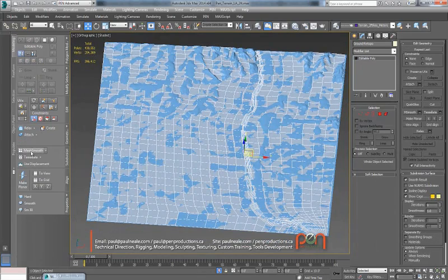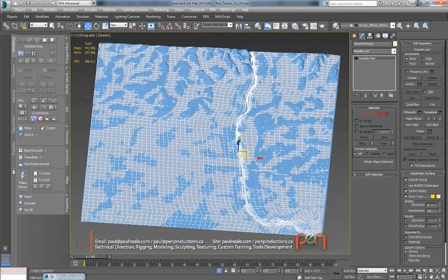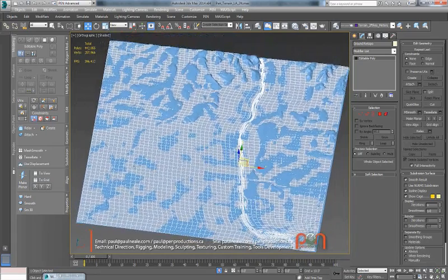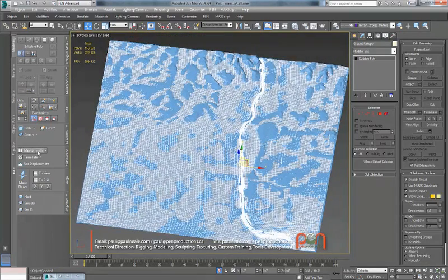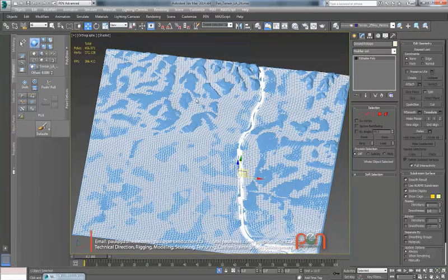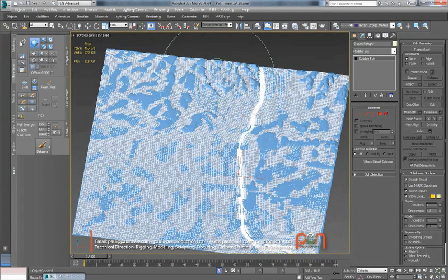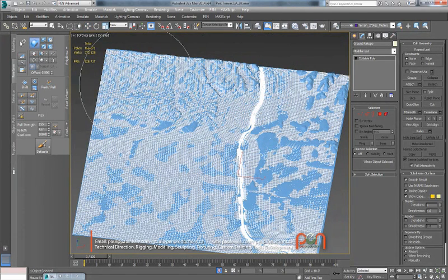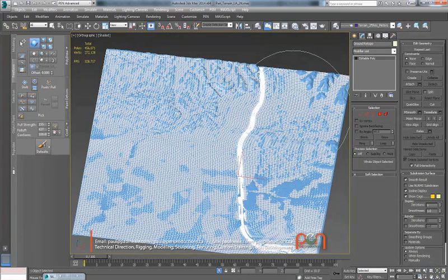I'm going to go back to our modeling tools, and I want to say mesh smooth, and I'm going to smooth it once. And maybe even again, just to get this up a little bit higher. So I'm going to say again. Now this is going to start slowing down our conform brushes. So as you select it now, it's probably going to take a minute for it to kick in and start functioning. And it's going to be a little bit slower to work with. So your conform brush may need to go down much smaller.